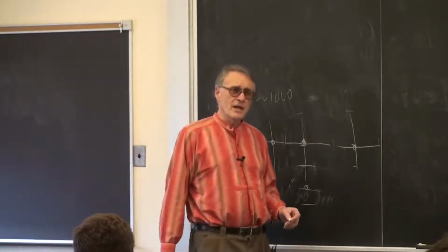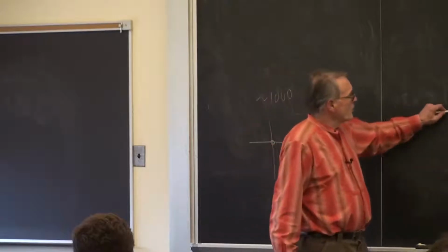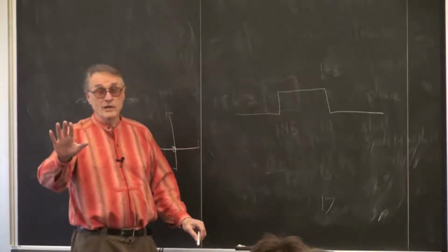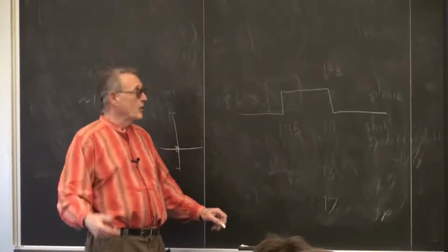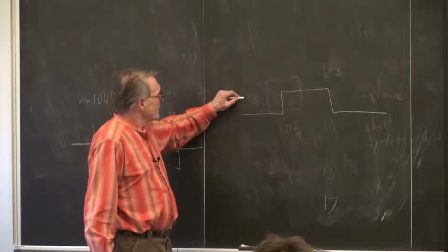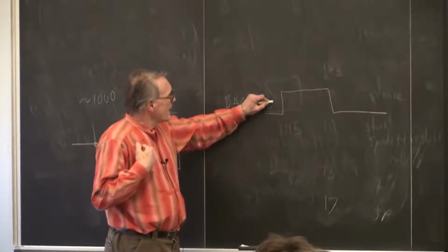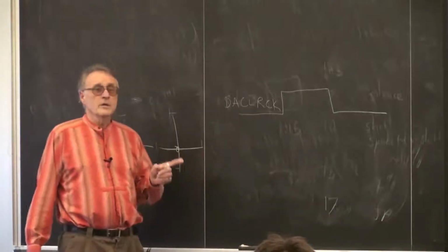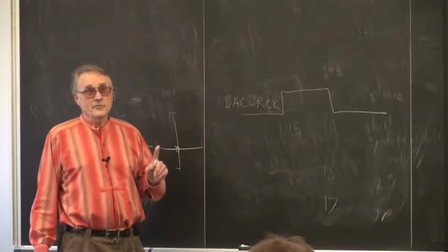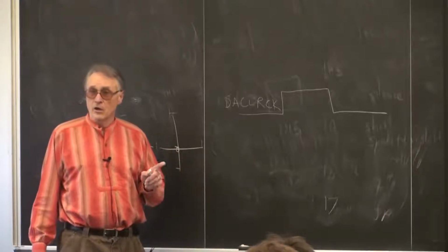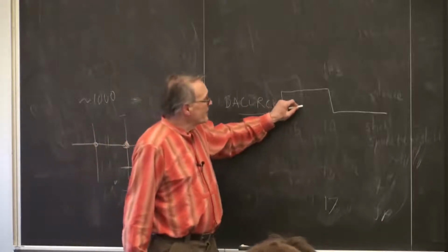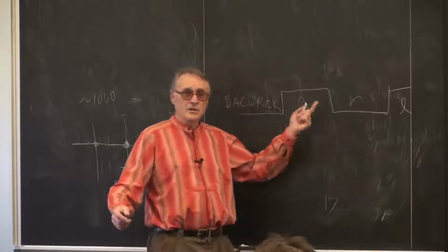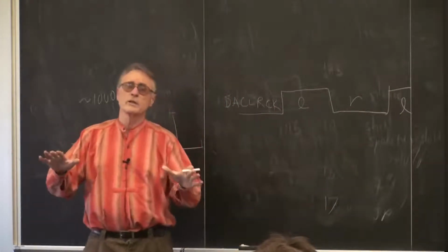Another way to do it, which I actually think is a little easier, is that one of the signals that exists at the output level of the FPGA, so it's on an I/O pin, is called something like DAC left-right clock. And it turns out that DAC left-right clock toggles at the audio sample rate, because it's saying, give me the left signal, give me the right signal, which is a serial protocol you really don't want to know about.